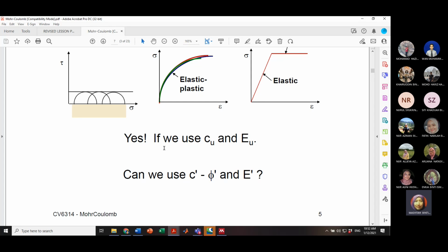If you have a sample in the triaxial, with the setting as undrained and then it is also a Mohr-Coulomb, but this time you will see that the strength parameters are undrained conditions, or in total stress, and the stiffness parameters are effective parameters. So that we call method B. So you will see the difference when you assign the strength parameters. Method A uses effective strength parameters, method B uses total stress parameters. Everything else related to stiffness is still the same, effective.